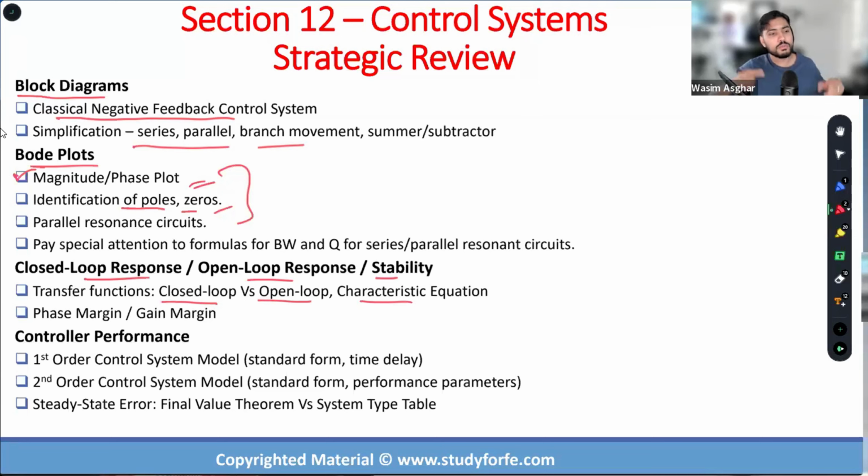When you have a closed loop transfer function, which basically has a feedback, if you sever the feedback and put it as a single string, then that entire relationship between output and input becomes an open loop. And the denominator of the closed loop transfer function equated to 0 becomes your characteristic equation. And there's a lot of information that we can draw from the characteristic equation, open loop transfer function and closed loop transfer function.